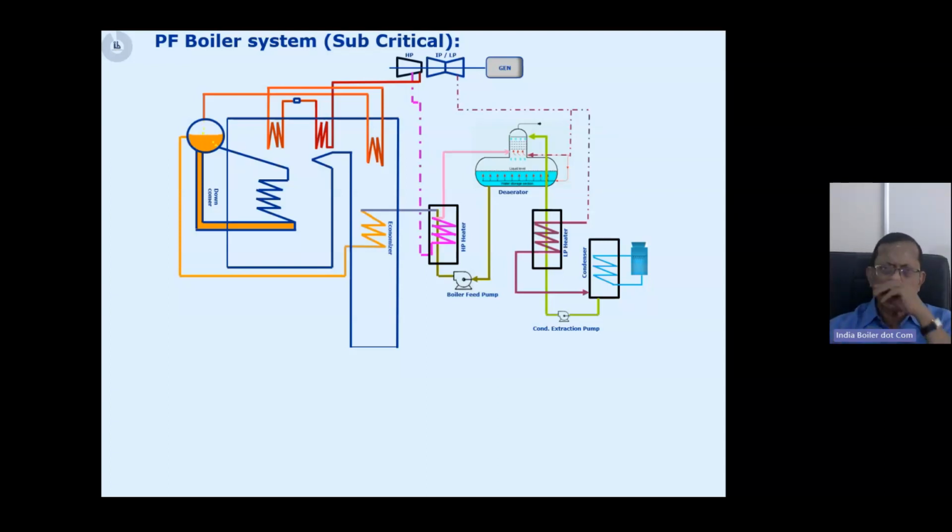Then that exhaust steam comes back to the boiler. But to maintain the main steam temperature, we have the attemperation spray. Sometimes it is two stage, sometimes single stage attemperation, and the spray comes from the BFP discharge, sometimes the HP heater outlet, most of the time nowadays.